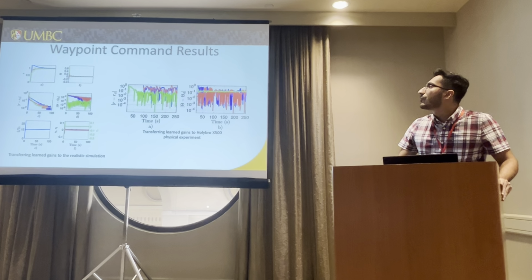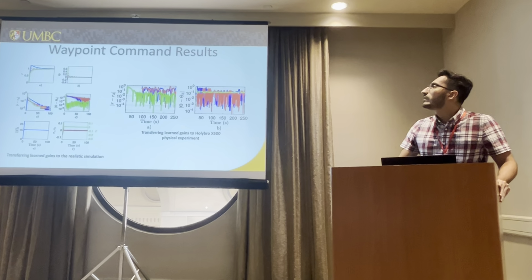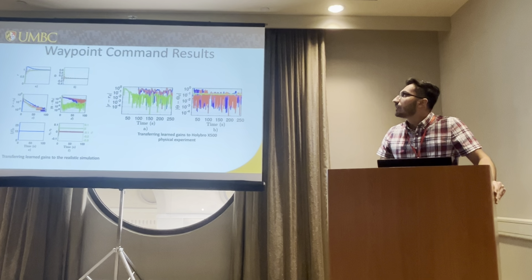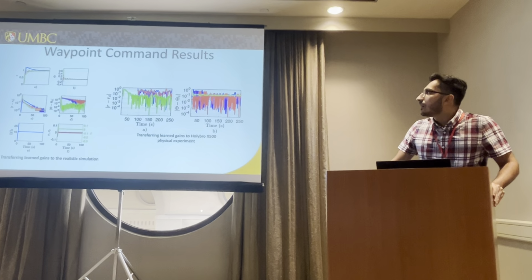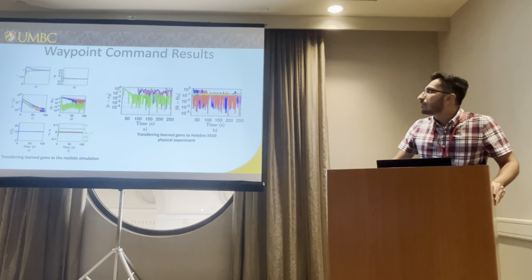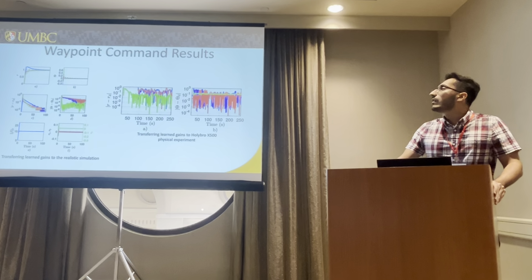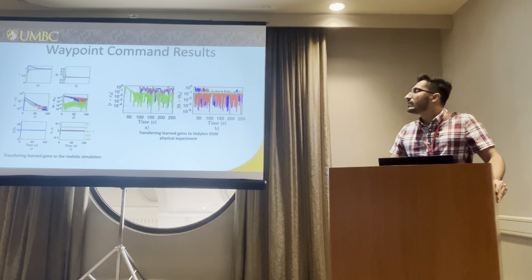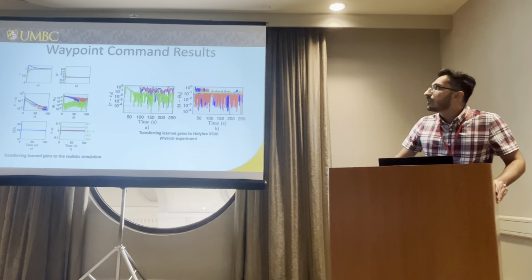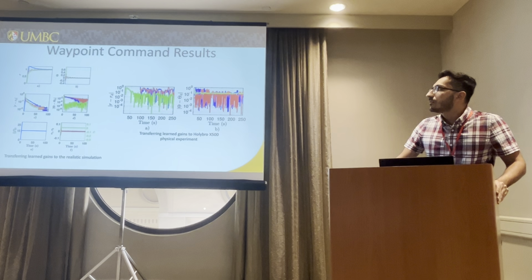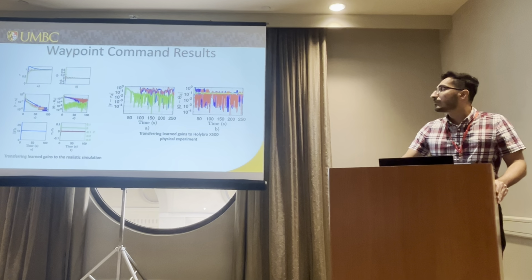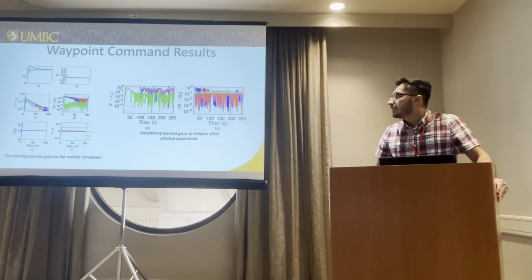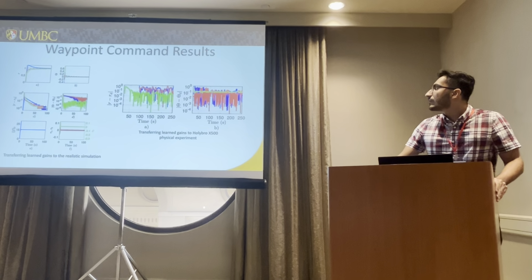In figure A, which shows the position of the multirotor, it is able to follow the waypoint command, and in figures C and D, we are showing the output error on a logarithmic scale. The errors keep decreasing. We have the error on the position, also the attitude parameterized by Euler angles. And figures E and F are showing the applied control sequence.